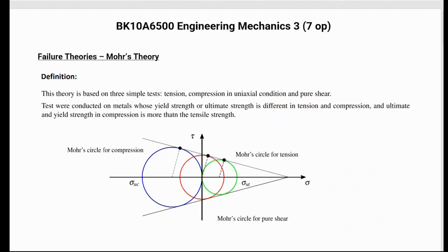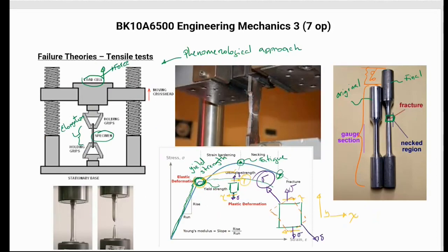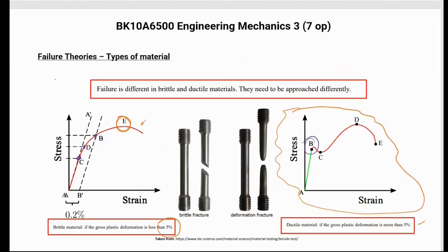Mohr is a little bit more complicated, but it uses, instead of yield stress, the ultimate strength. I'm going to take this figure, something in this vicinity, but applied to brittle materials, it should be something like in here.